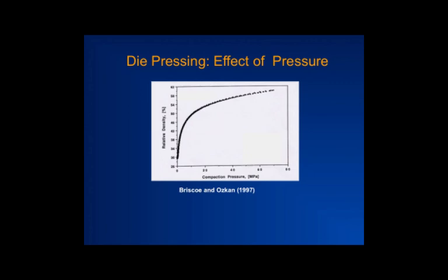And okay, so basically green, yes. If it's a metal powder, you can deform the particle, but otherwise all you're doing is trying to push the particles closer and closer together and eliminate some of the porosity, right? So if you have agglomerated ceramic particles, you might be able to break up some of the agglomerates as you're pushing it together because they are weaker and it'll rearrange.